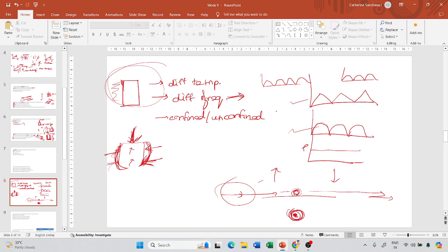Now when you do this, researchers have said that out of these two types of loading, a Haversine load represents close enough to the stress experienced by a point in the field. So here also we are going to adopt Haversine loading. It is actually a sinusoidal loading.